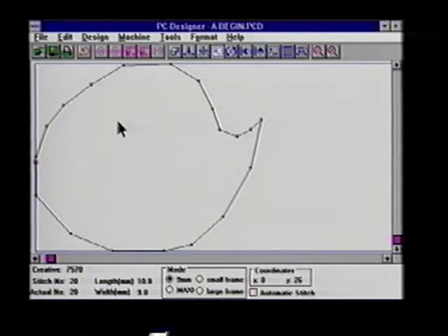That is a definite advantage with A fill-in, that it can be an open area, an option that is not available with B fill-in. First, click on the stitch just above the straight portion on the left. Shift and click on the stitch at the right point. Press Enter to retain the highlight of this portion. This is now the first side.